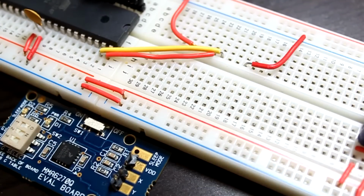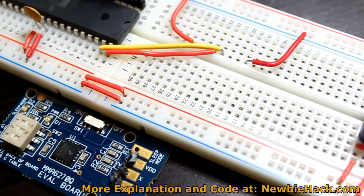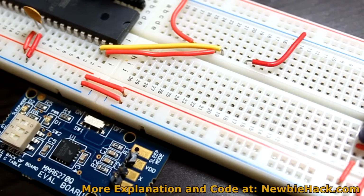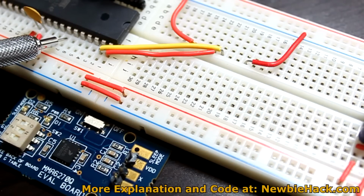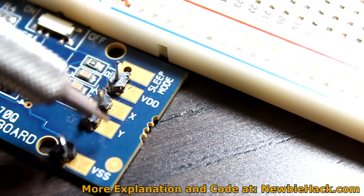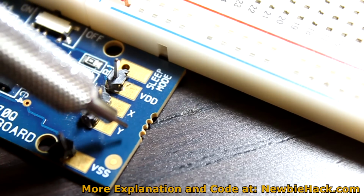In this video, I'm going to demonstrate the use of two ADC channels. In the previous ADC videos, I've been using channel 0, which is ADC 0 here. If we would like to read another analog signal, we can use other channels along the ADC pins. Since my accelerometer has both an X and a Y axis, and we were reading the X axis before, I'm going to start reading the Y axis.